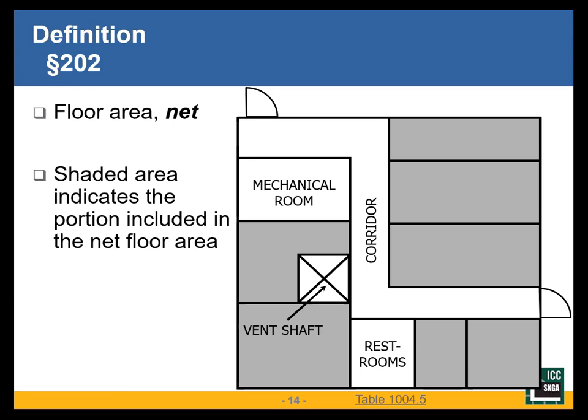And if that higher occupant load has adequate exiting, I come up with 120. I have 2 exits. I've met the requirement for 120. I'm done. I've complied. I did not have to go through and calculate the size of the restroom, the corridors, or ventilation. I didn't have to go through that math. Take the entire floor area, ignore gross or net. If the building complies based on that, it will comply based on gross or net, because you're being more conservative